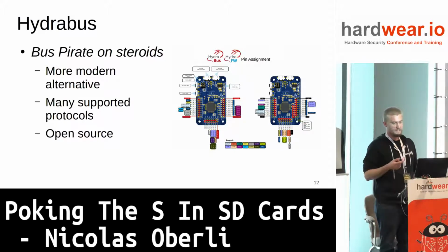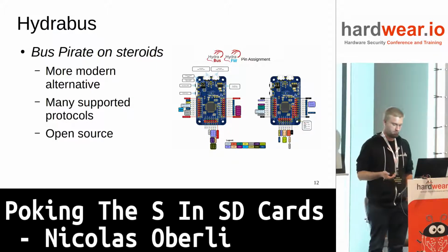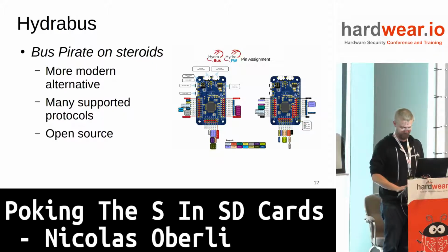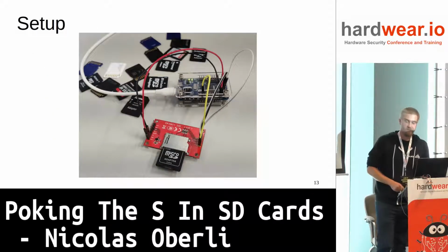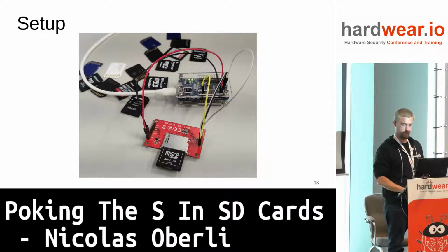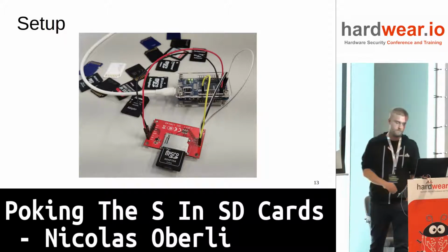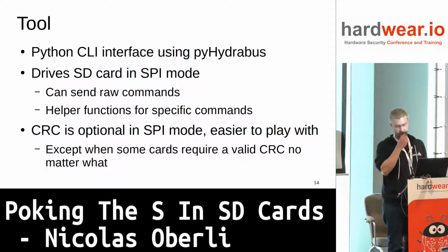What is HydraBus exactly? Basically, it's like a Bus Pirate, but a more modern version supporting more protocols. It's also fully open source. Good stuff. So my main setup was basically a HydraBus with the SPI interface connecting to an SD connector. So it was not the worst part.